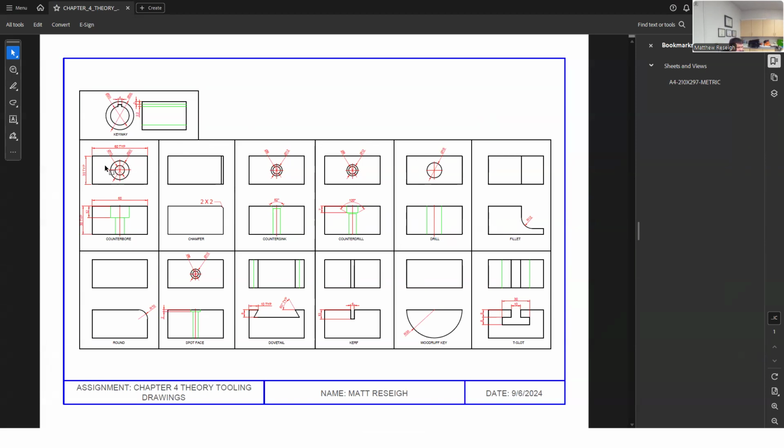And then I made a 30 by 60 block. Essentially, and I've talked through this, what these are is a front view and a top view. This is like a multi-view projection. Only two views are needed. The reason we only need two views is that the other view might not give us any new data, so it's not needed to have a three view. These are technically the first little multi-view drawings we do, where we have a top and a front view of a block. This thing is really just a block that's 30 by 60 by 30.